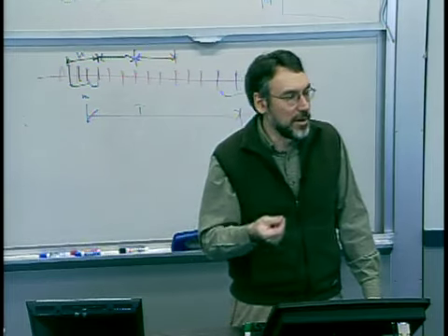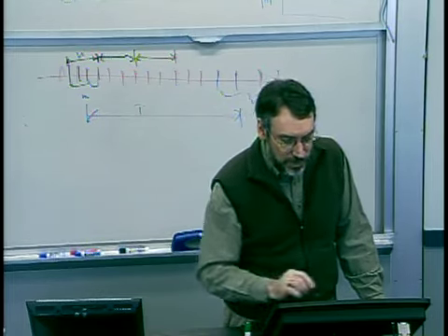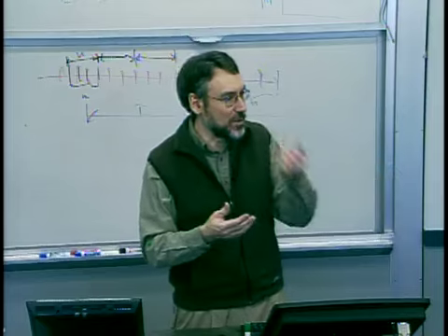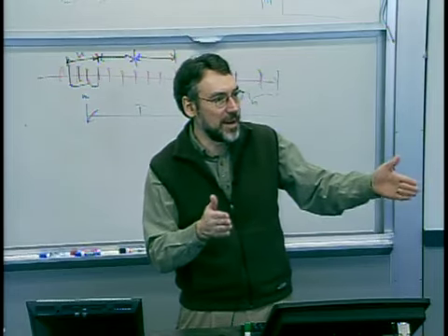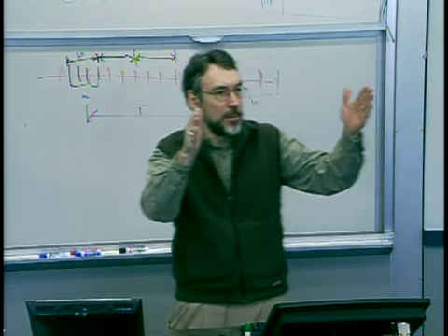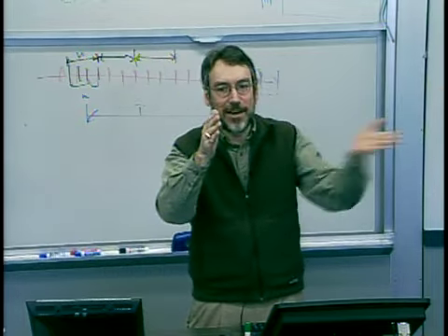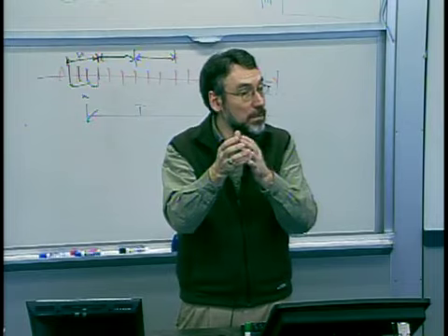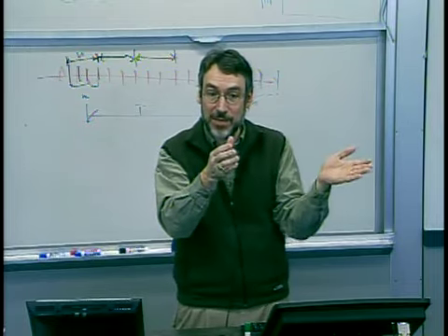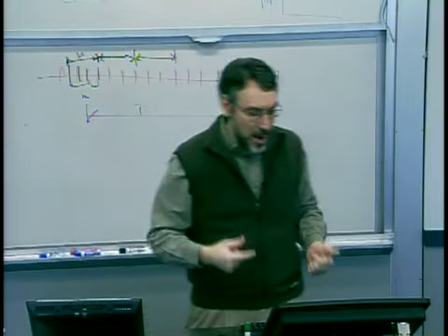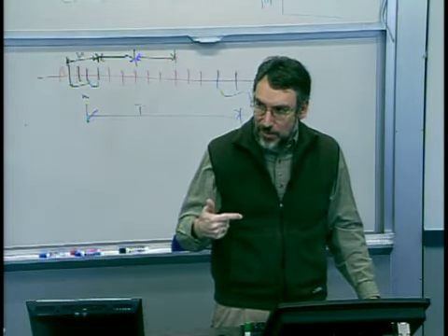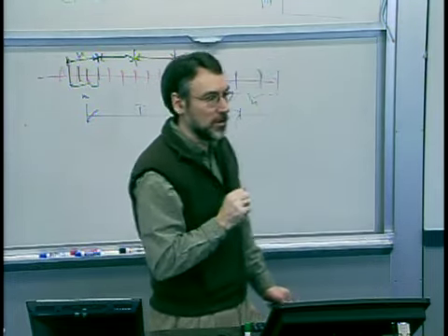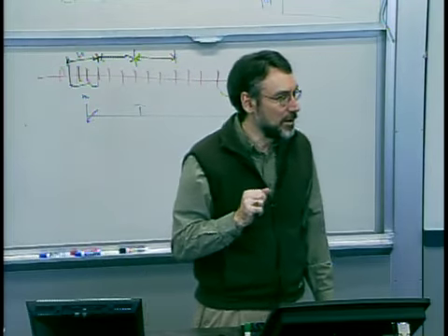So an approach here is essentially use a variant referred to as a running control chart or a running average. So you look back not just on the new sample, but some number of previous data points and have a window that moves along or some calculated average of past history where I might weight my most recent measurement either equally or more importantly than my past measurements, and use that as an estimate for the process average and the process variance. Does that violate the independence assumption? Absolutely. It does violate the independence assumption.